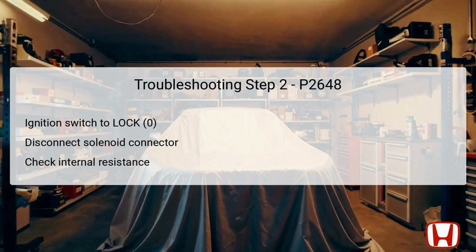The following check focuses on measuring the internal resistance of the rocker arm oil control solenoid using a multimeter. Technicians should verify continuity between specified test points on the 2P connector. The expected resistance range at room temperature is 14 to 30 ohms. If the resistance falls outside this range, it indicates an internal failure within the solenoid, necessitating replacement.